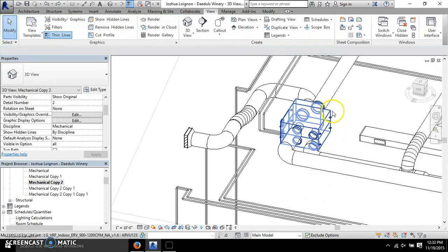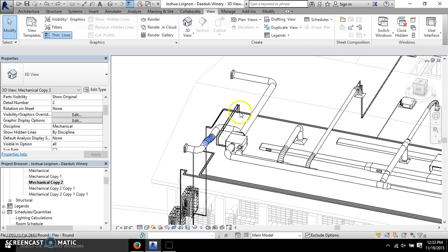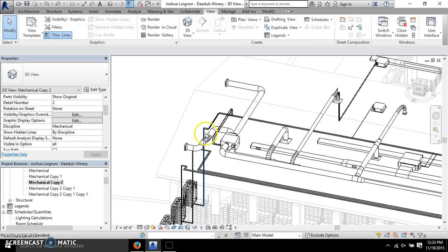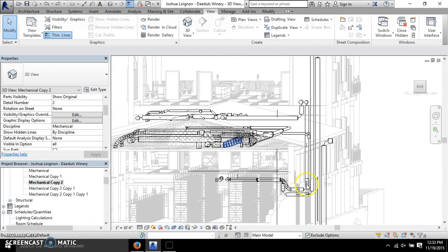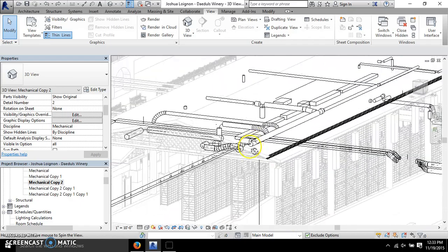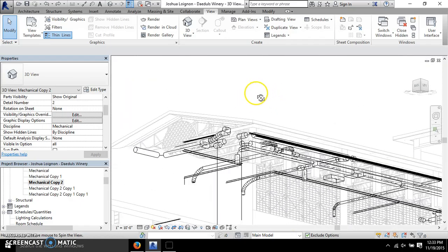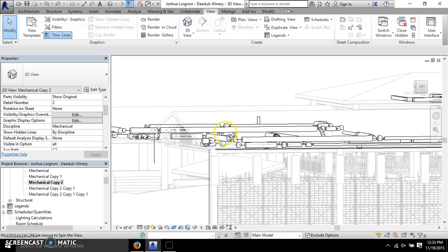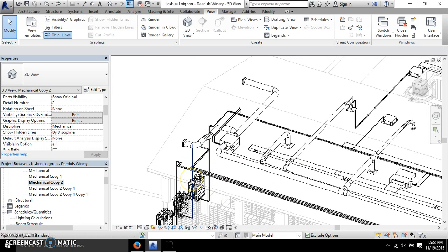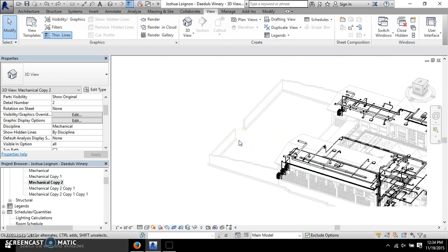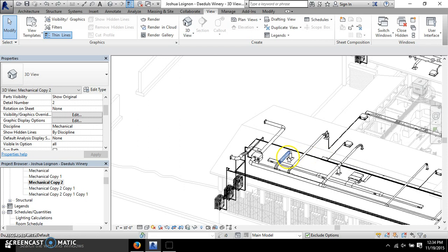And then from the air handler unit, you have one duct that's outside air that's pulled in, and then you have a louver on the outside of the building, on the facade. I have it hidden, but if I switch to another view, you'd be able to see it on the facade. So you try to hide the louvers if you can, or incorporate them into the design. Obviously, that's what you would want to do. A lot of people don't do that.